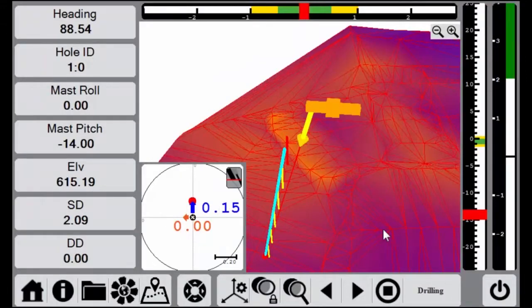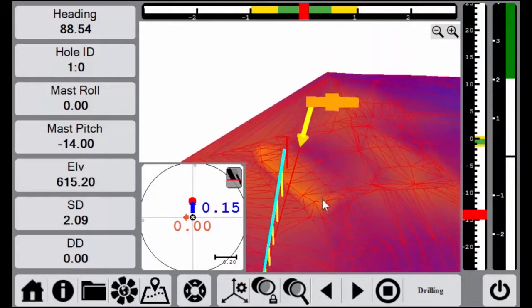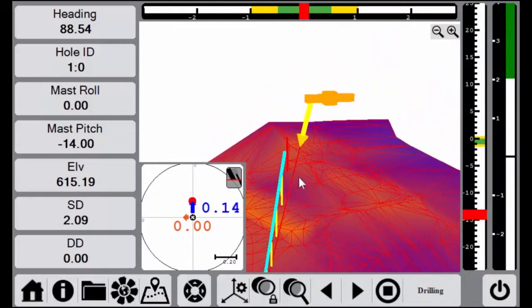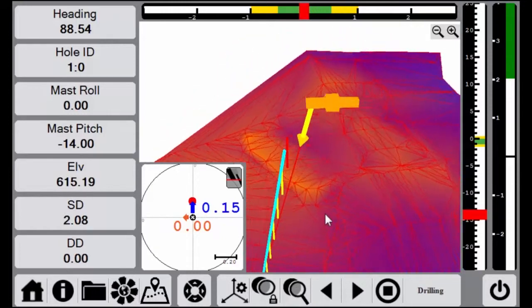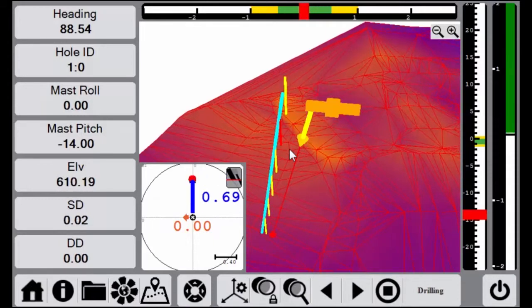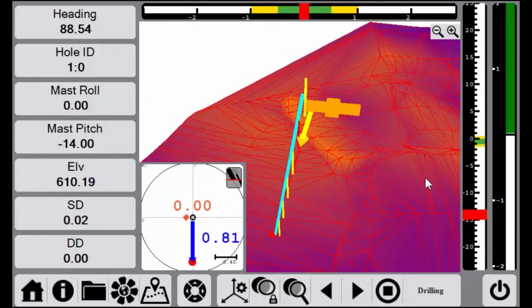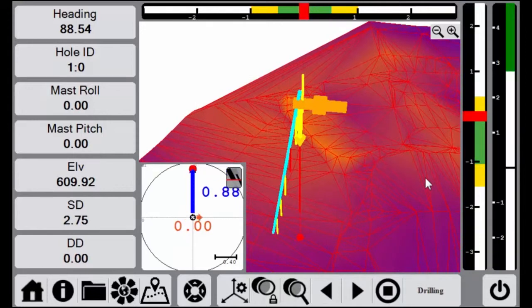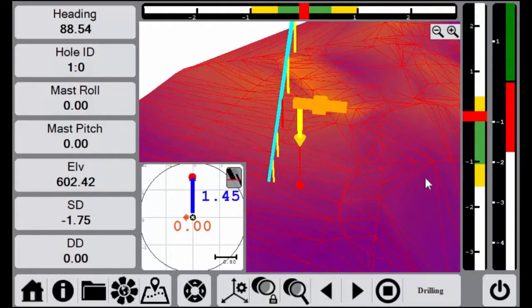accept, you can see that that one drill hole has been separated into multiple benches to help me get to that design bench elevation. So the currently active bench is going to be highlighted red. And if I were to use the emulator to move my machine down, you'll see it goes down to a different bench, which I'd go navigate over and match the inclination. And then as I go lower, it's the next bench below.